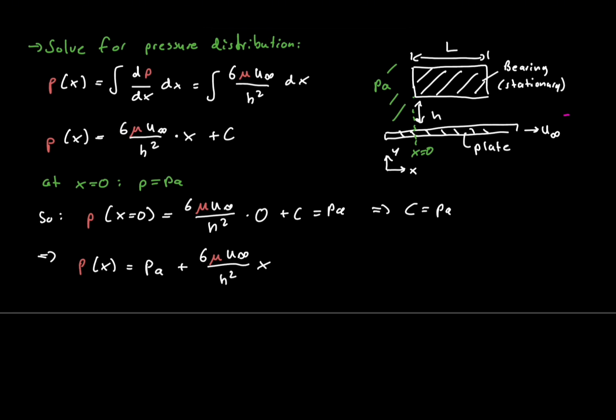This result shows the mechanism of hydrodynamic lubrication. The moving plate tries to drag fluid forward. Because the fluid cannot escape, pressure builds up and creates a backward pressure-driven flow that cancels the net flux.